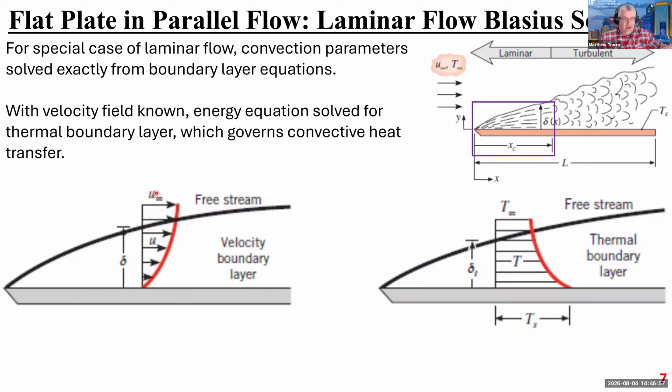There is in reality no actual physical line in space that you can point to that says this is the boundary layer where things change, right? It's just a subtle difference in the velocity, but that line is basically drawn for the spot where 99% of the free stream velocity is achieved, and basically the end of the momentum influence of the presence of the plate.